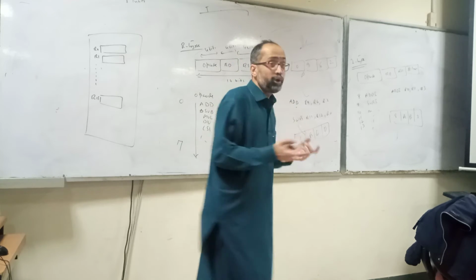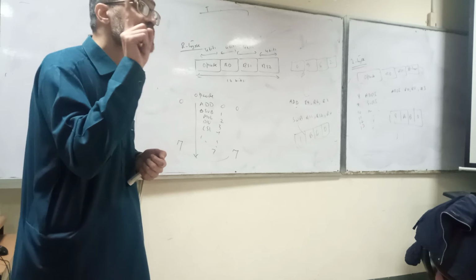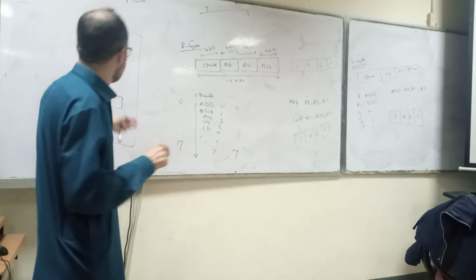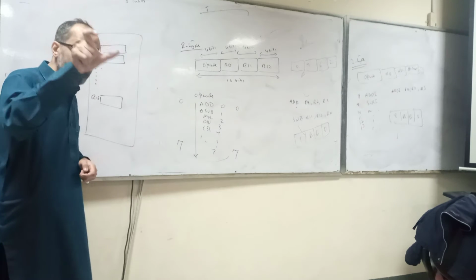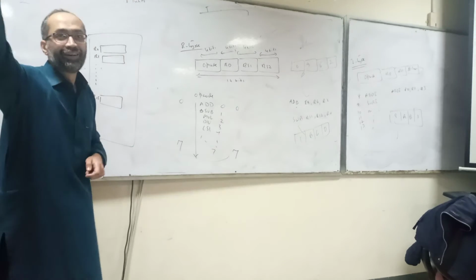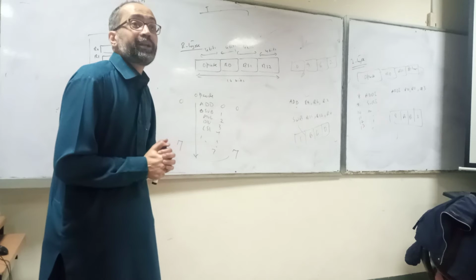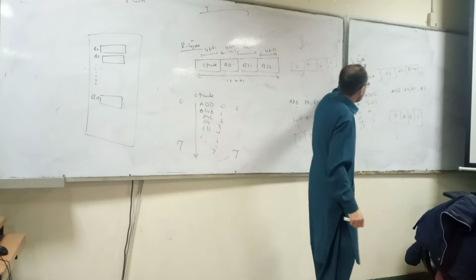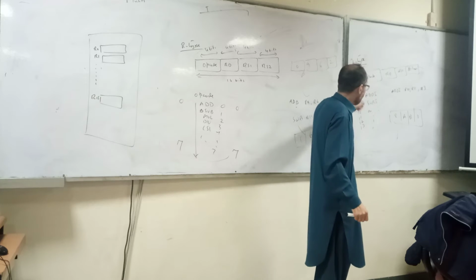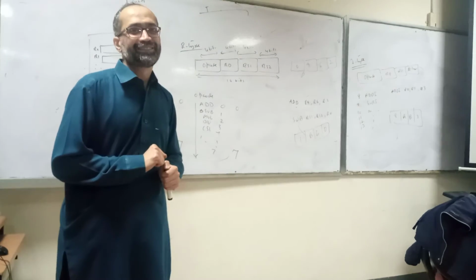Okay? And if you want to increase the number of registers, which field do we need to increase? If we say 32 registers, we need to increase the number of bits allocated for the RD field, RS1 field and RS2 field. If we want to support more opcodes, which field do we need to increase? The opcode field. Okay, now because this is an I type, if the opcode lies within 8 to 13, it means that it is an immediate instruction.